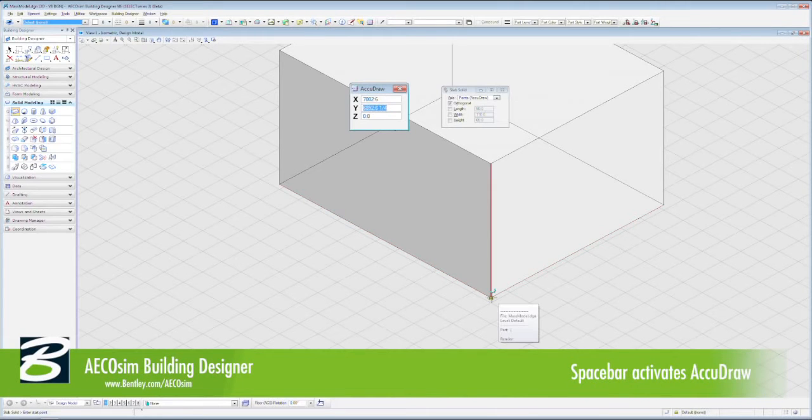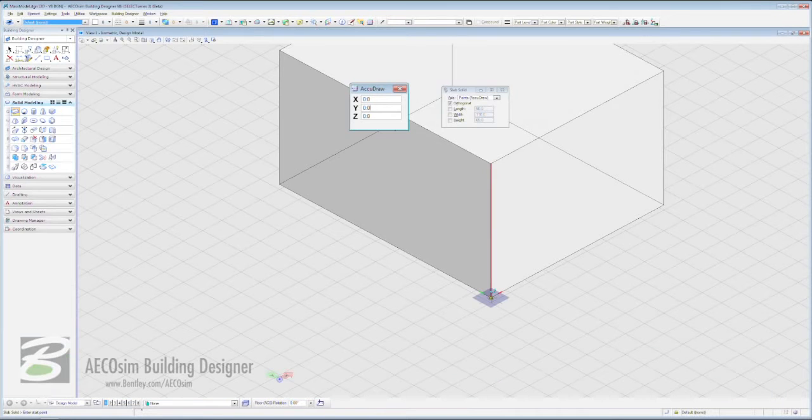We're going to press the letter O on our keyboard. That gives us a temporary origin point to start from. This is where we can offset from very quickly. The first thing we need to do is offset by about 30 in one direction and 15 in the other direction. So you can see straight away, all we need to do now is click. And that is exactly a 30 by 15 offset from that particular place.